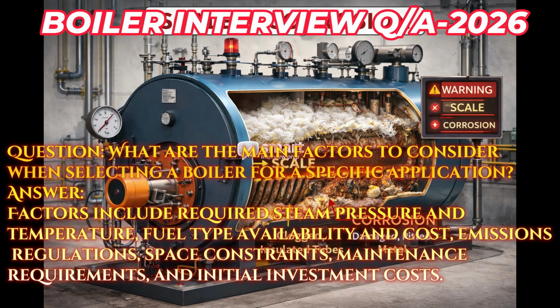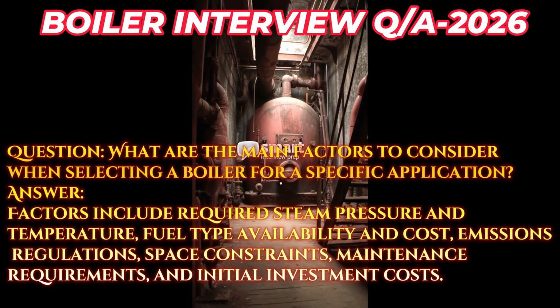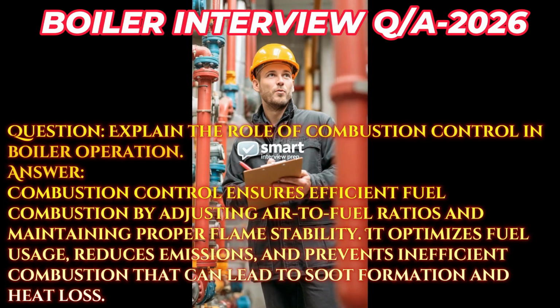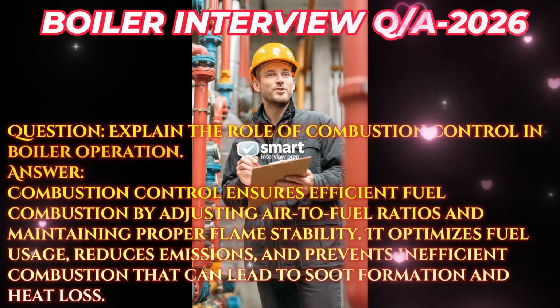Answer. Factors include required steam pressure and temperature, fuel type availability and cost, emissions regulations, space constraints, maintenance requirements, and initial investment costs. Question. Explain the role of combustion control in boiler operation.